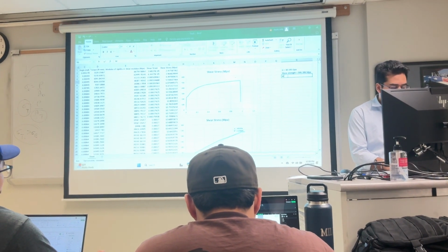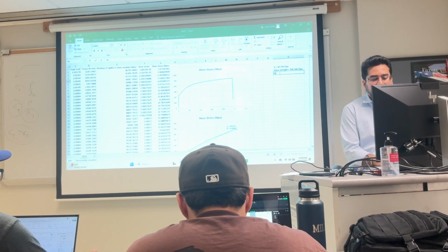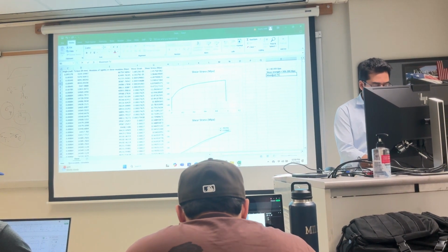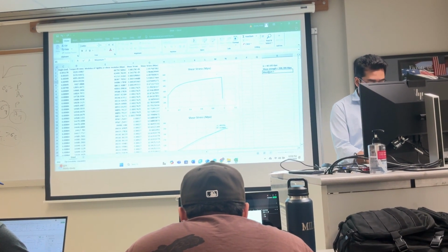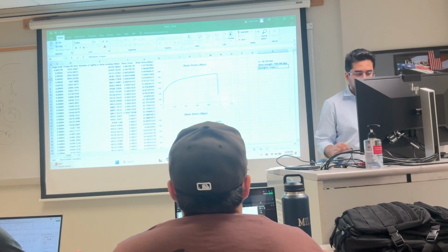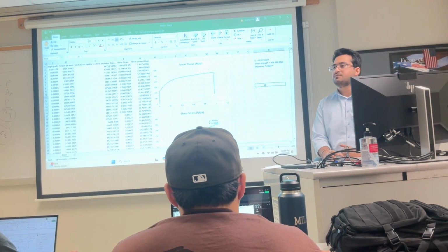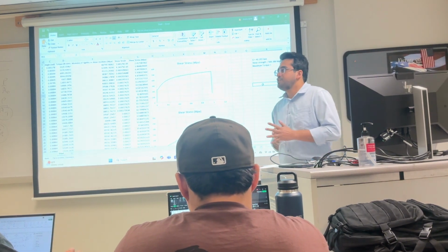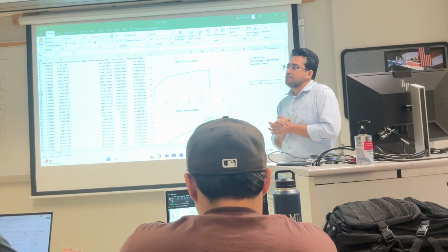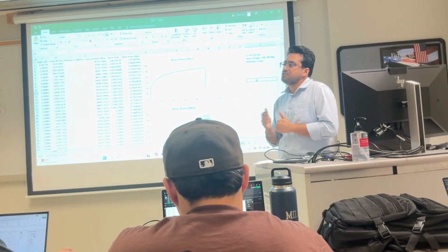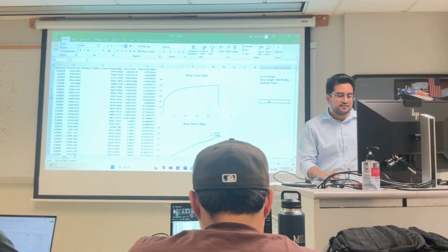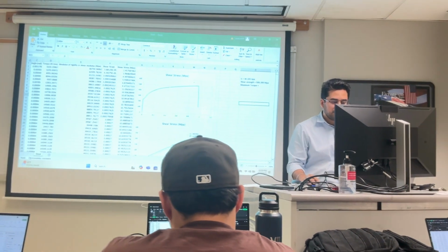Okay, now I'm going to calculate the maximum torque because I need maximum torque to find the power, right? I got 685,970. Yes, exactly. How are you going to find the maximum torque? If you see the formula, shear stress is TR by J. R is constant, J is constant, that is not changing. So basically, if we have a maximum shear stress, torque is going to be maximum at the same point. Just see where this number lies, 506.386.